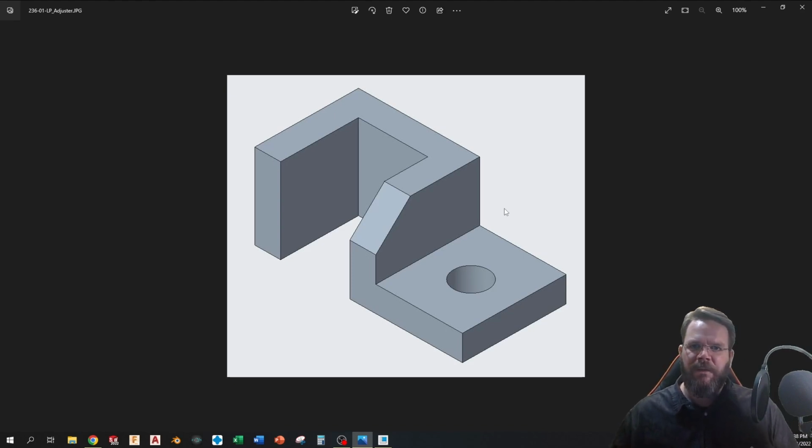So if we look at this, I've got this little offshoot here. This is one feature. I've got a wall here, I've got a back wall here, I've got another side wall over here. I've got all these different features. Now I could create this, and that could be our base feature, and that's valid. That would absolutely work. Or I could ignore this little cutoff and create this L shape here. That could be our base feature. Would absolutely work. Or what we're going to do in this video, I can select this rectangular arch here.